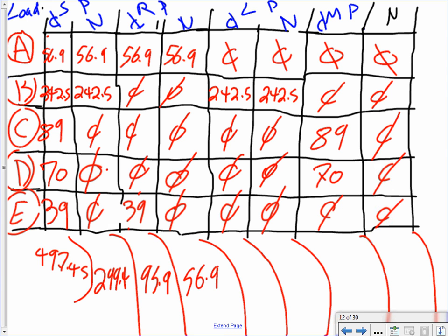They're on balance. The second panel, guys, I have 242.5. The neutral will also be 242.5, all the lights. The last panel, I have 159K, all of them are K, and the neutral will be a big fat fluffy 0. This is the load for all the neutral and the phases on these panels.